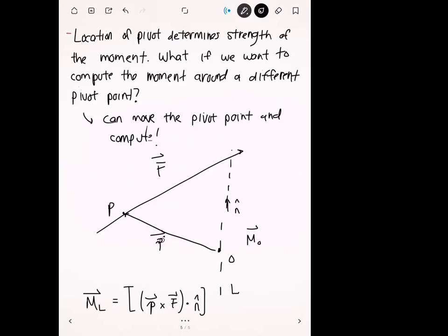By projecting it onto the vector n, we basically found the component of the moment on that line. And in order to keep the result as a vector, we're going to multiply that whole thing by the vector n as well. With this formula, you're going to be able to basically project any moment from one axis onto another one. Any questions on this?